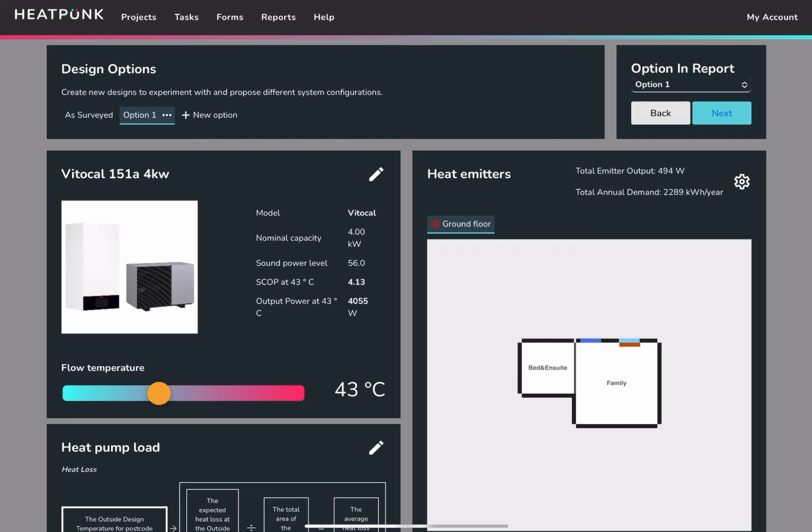And then we will take a reading from that, and we will compare that to your existing incoming cutout fuse size, so that we can report all this data to your district network operator. And that's another series of forms and applications we have to go through once we have this data. And that allows them to know that there's going to be an increased demand in your area and whether your existing supply is adequate to handle the loads of a heat pump.